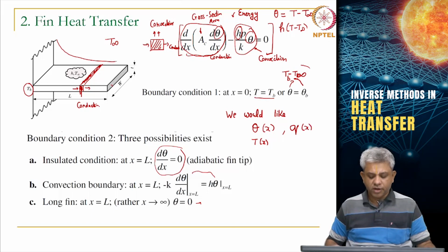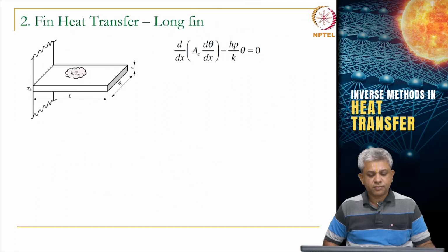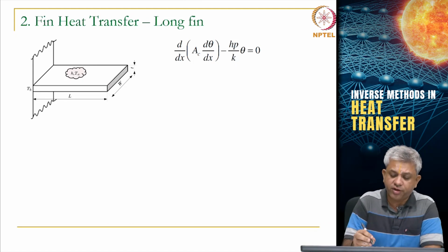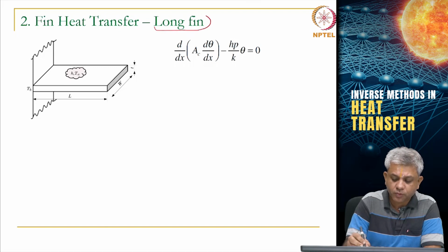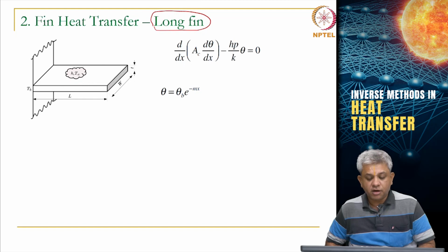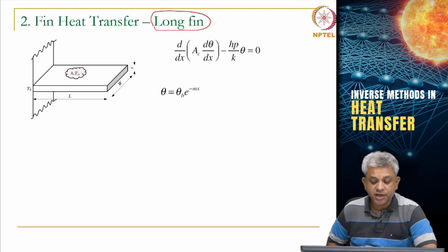Temperature and heat transfer are the two quantities that we are interested in. If we go ahead and do that, what we would find, for the specific case of a long fin, which is what I am going to solve for, is a simple expression: theta is theta base multiplied by e to the power minus mx. So let us now derive that.